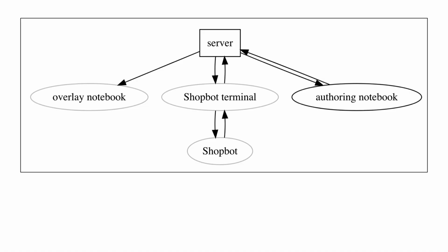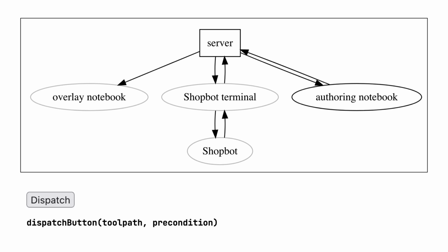To support the library, we developed a network architecture to connect the Shopbot with the user's notebook, as well as an augmented reality overlay for visualizing movements on the Shopbot's physical bed. Code executed in the notebook directly affects both the Shopbot and the overlay. This eliminates the need to export and import files from separate programs, which is normally required.